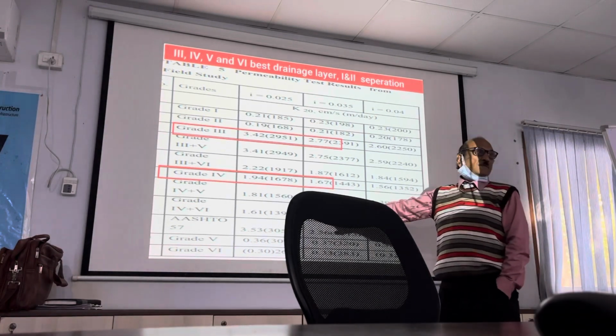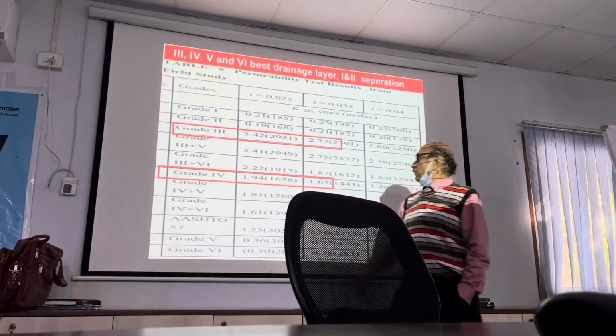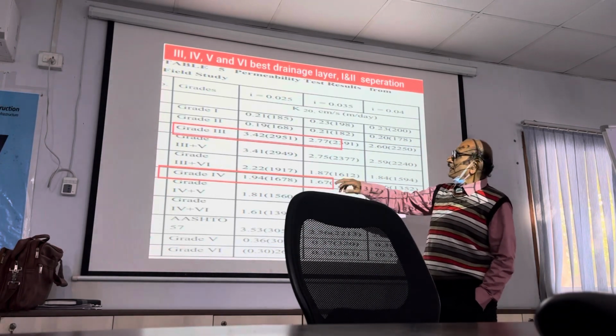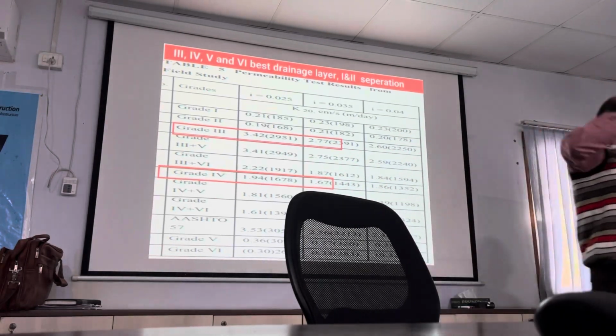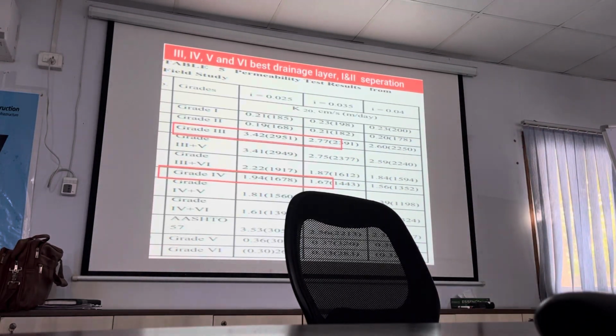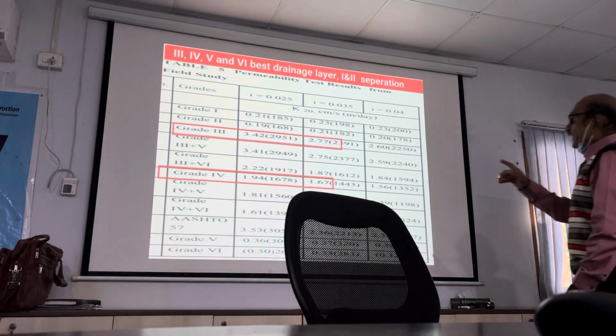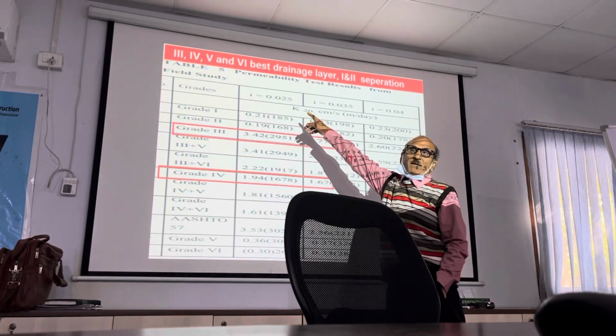What we have found, the permeability of grading 4 and grading 3 is highest, 3000 meter per day. We need only 300. All the gradings almost have permeability more than 300 meter per day. So as per rule, we can use any grading as a drainage layer, GSB layer, as per code. But for your advice, they say this is bottom, this is top. Now, they did permeability at 2.5% camber,